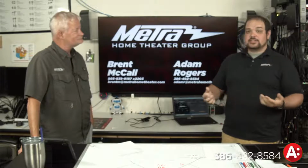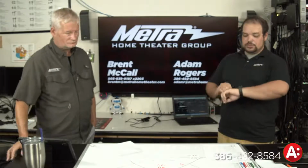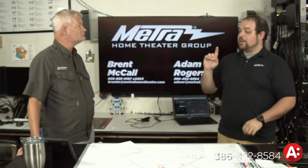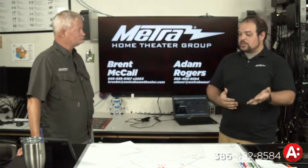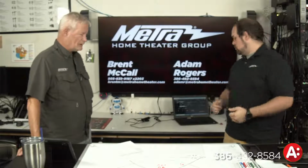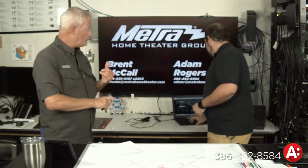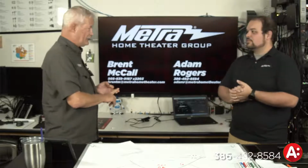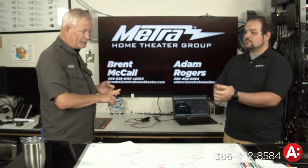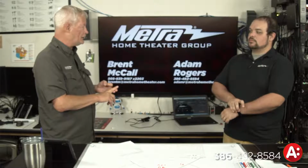Yes, it works on Cat 6, which is the standard that you should be using for HDBaseT, but it's better to use the better cable because you're going to increase the lifespan of your transfer device. And the reality is, whether it's networking, cameras, or HDBaseT, you really should be laying in Cat 6A now. Yes. Cat 5e should be nothing more than tying your trunk closed.